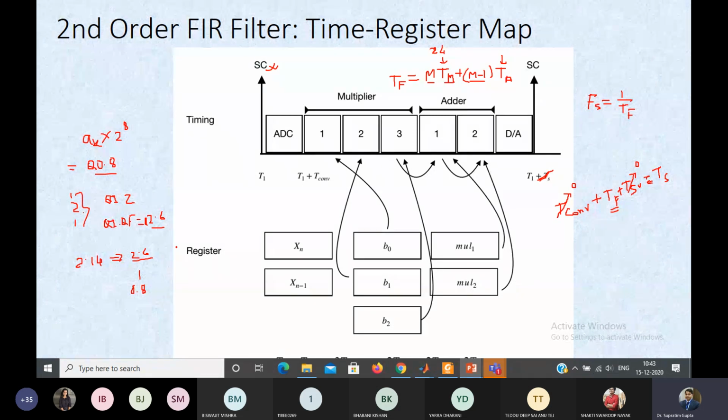Now if V reference is 5 volt, it is 3.5 format, right? So how can you do that? This is very easy. This 2.6 format can be converted to 3.5 format just by right shift. And then you use the 3.5 format representation of the reference voltage, and then you divide it, you will get the 0.8 format, and then you place this value to the DAC.